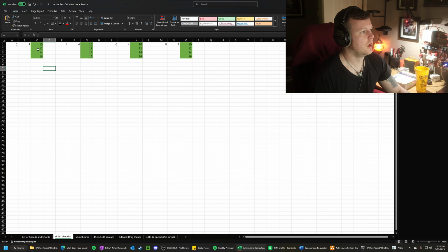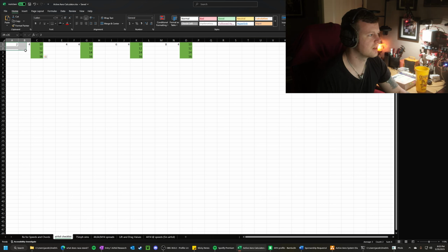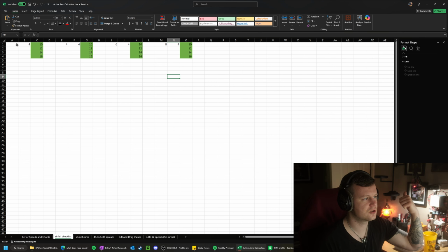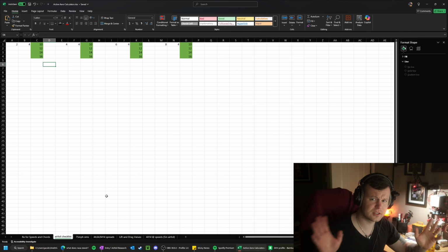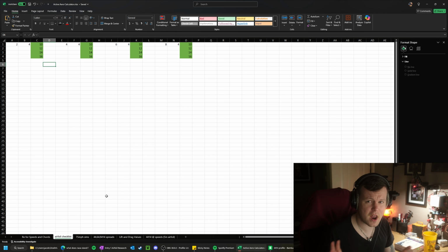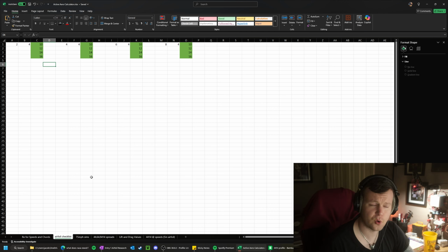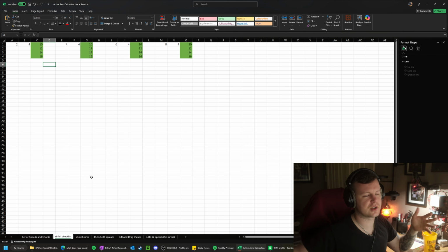So I just had a little, not cheat sheet, but a list of the airfoils that I wanted to analyze. So I wanted a 24, 44, 64, and 84. And then the last 2 digits I did 10, 12, 14, and 16. I looked at a handful of them and kind of got the limits of what I thought would be good to analyze, because I had to narrow down what I was looking at. And from my research, I found a lot of people use 4414, 4412, and I saw a few 6414 and 6416. So I was like, all right, let's get a few airfoils to either side of that to start looking at.